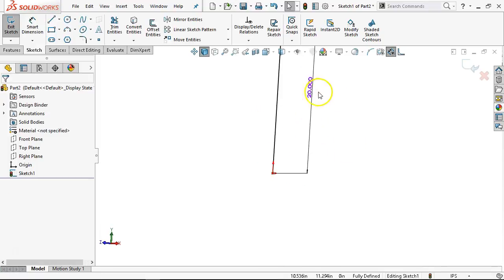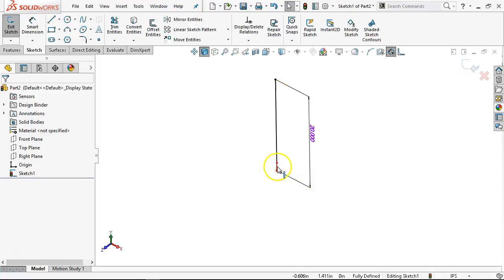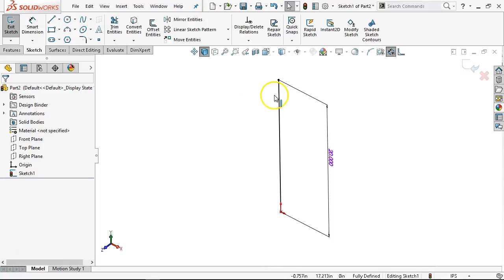All right, so if I want to just generate the sweep, this could be a spline and have the wave through it and do whatever it does, and whatever I generate as the profile will just follow that wave, right? But we're going to drive this with guide curves, so the direction is generally up, generally in a straight line, and the guide curves are going to control the bulges, the indentations, the which way this goes.